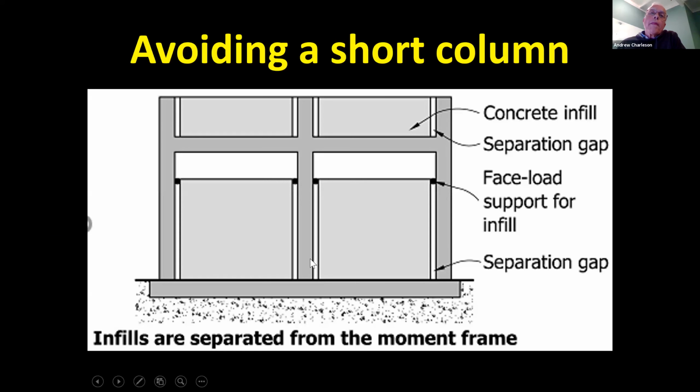Yeah, so the gap here, the thickness of the gap depends on the flexibility of your moment frame. But typically, these gaps are between 2 centimeters and 4 centimeters wide.